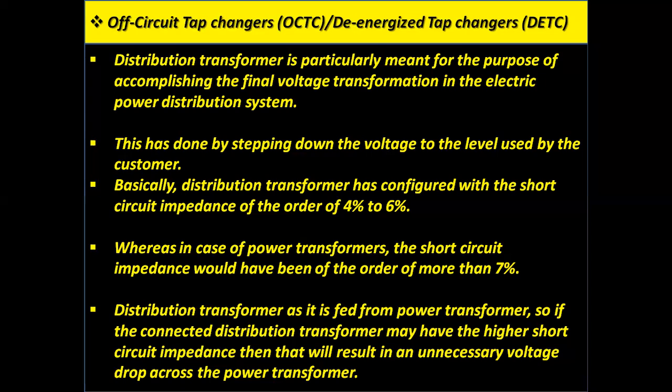The most important point is that the distribution transformer is fed from power transformers. So, if the connected distribution transformer has a higher short circuit impedance, then that will result in an unnecessary voltage drop across the power transformer.